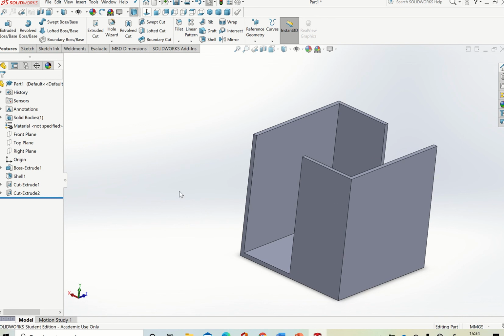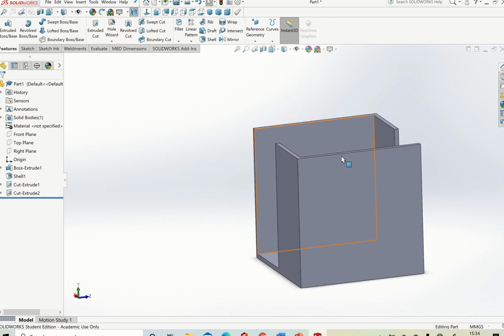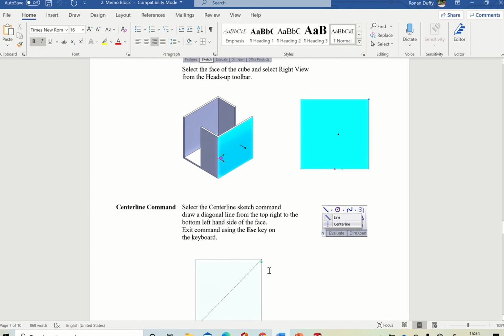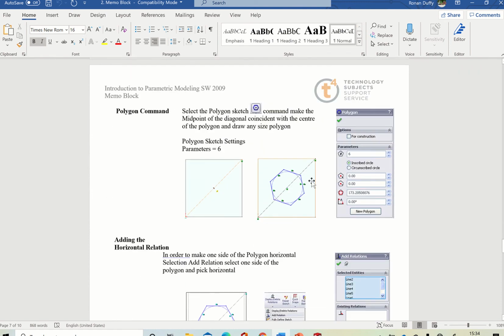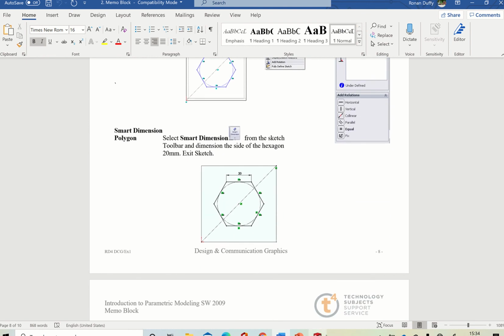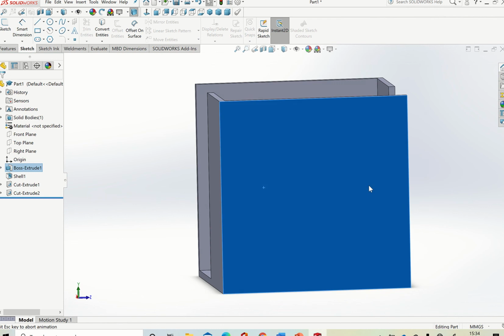And you'll notice then that we have to make a cut. We're going to make a hexagon. It doesn't generally matter what shape you make here, but it says in the Word document to make a polygon or a hexagon, so that's what I'm going to do. So if we just go down here, we're going to highlight this, bring it up, then we're just drawing one axis line, and I have a hexagon here, and the dimension of that is going to be 20 on each length. So I'm going to bring that up normal too.